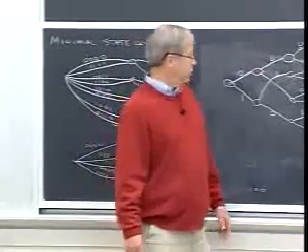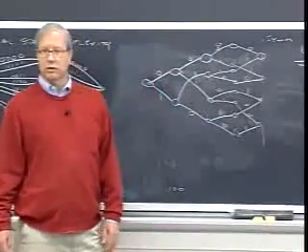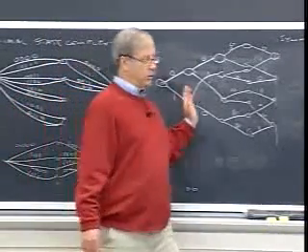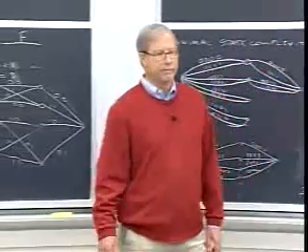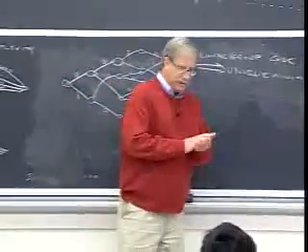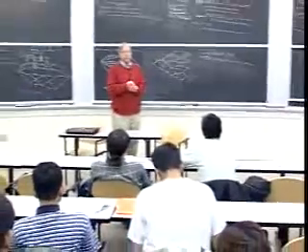And from an engineering point of view, once we've got this minimal trellis, we can use the Viterbi algorithm to do maximum likelihood decoding, just in the same way we did for convolutional codes, sweep from the starting node to the ending node. Okay, digest that, and we'll come back and talk about it again, do a few more details on Monday, but that's the basic idea.